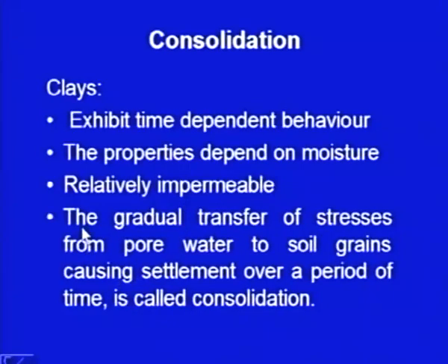And here is one of the definitions. There are several definitions of this term consolidation. This is the concept: the gradual transfer of stresses from pore water to soil grains causing settlement over a period of time is called consolidation. So, let me explain it this way: a building is constructed over a clay stratum.